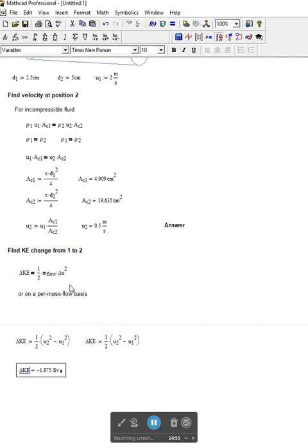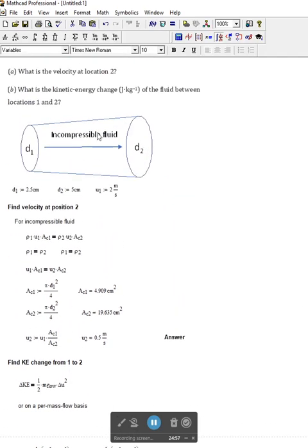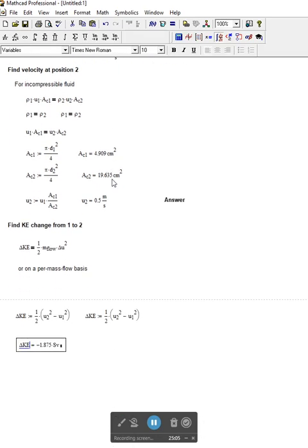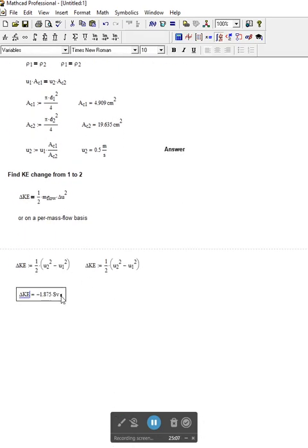If I am giving you a problem where I specifically ask for certain units in the answer, you need to have those units in your final answer. So what do you do? Well, one thing you could do is go to some arcane electrical engineering handbook and figure out or look up online what the conversion factor for joules per kilogram to sieverts is, or I can just let MathCad do the work.